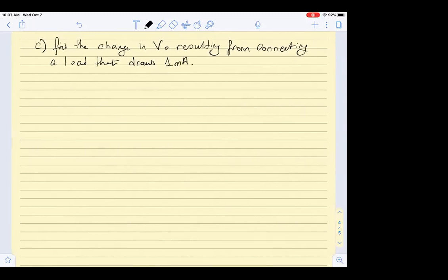Let me ask you this question. In the initial case, when I had V plus, a resistor and then the Zener diode with no load, how much current was the load drawing? What was the current being drawn? With no load, I have R equal to infinity, right? How much was the current for R infinity? It's zero.